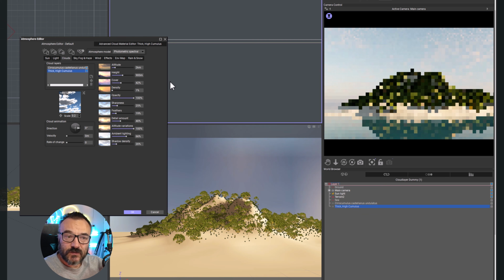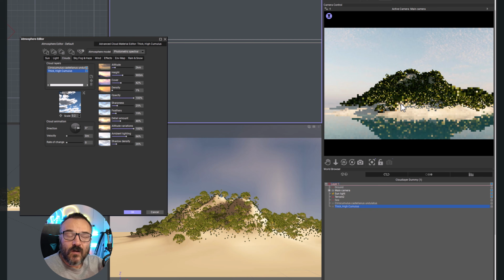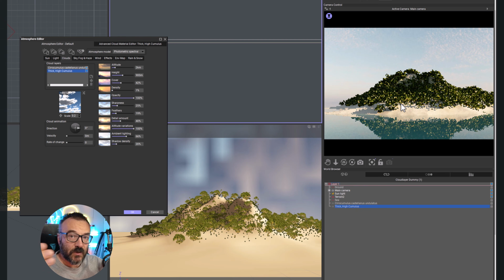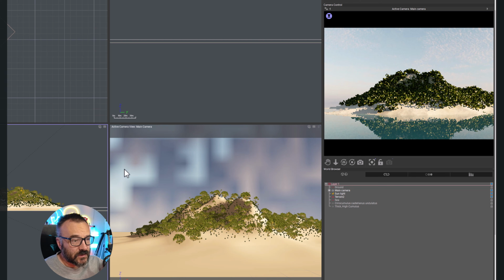Well, perspective. What I meant is, when we look in the atmosphere, right now it does not look very realistic because we're looking in two dimensions, it's not three-dimensional. And in two dimensions, there are several options that give us perspective from the distance. One is losing contrast, it's less contrast because haze will take it. Saturation reduction and reduction in details. We already have it preset on the details. However, we can use aerial perspective, increasing here to reduce some of the contrast far away and reduce some saturation. So I like to increase a little bit on this.